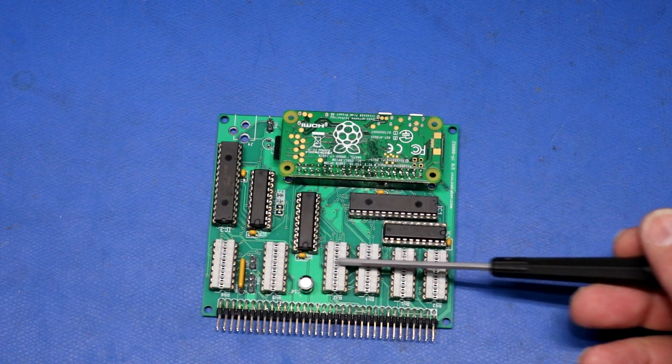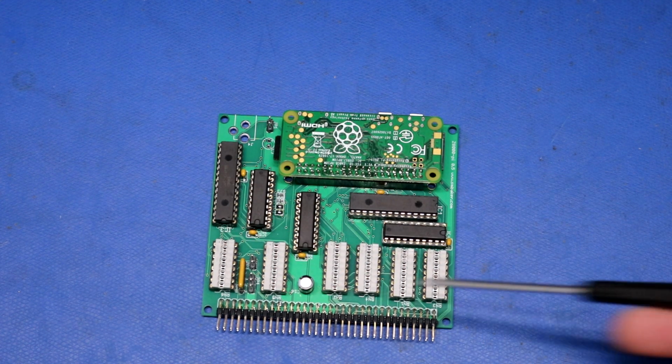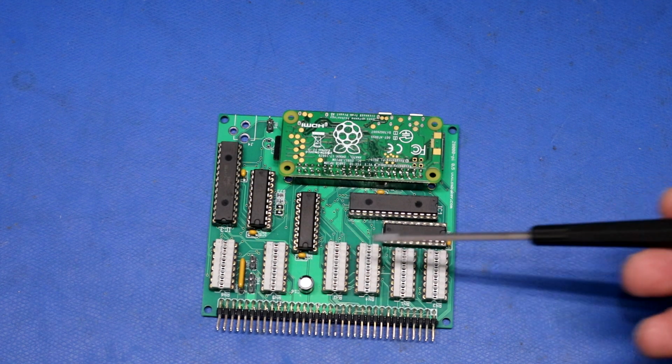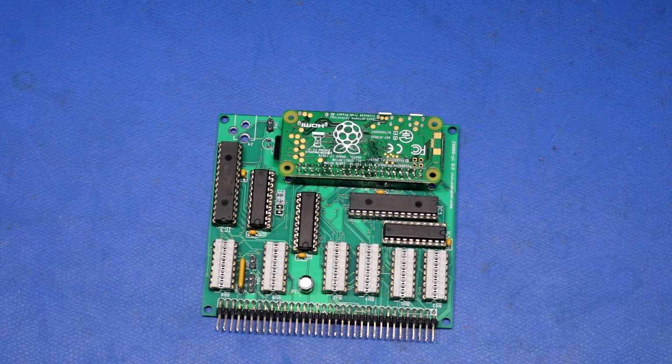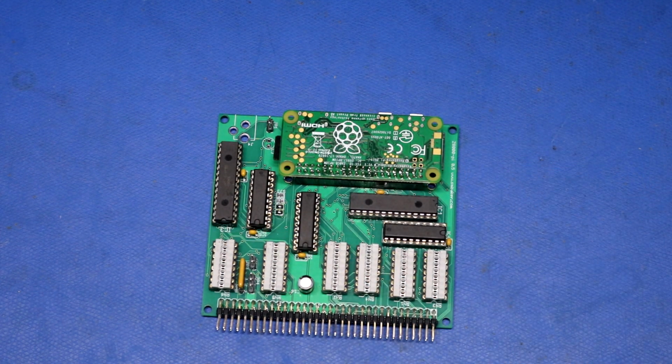This here will be removed, these shunt blocks, from the future revision of the board. They were so I could put resistors in there just for safety purposes so we don't fry anything. But once you get it debugged, you don't need resistors anymore. So these are just straight shunted across. Ignore them. Then we have various buffers as well as a pair of MCP23017 chips. Relatively straightforward build. Next, we have a speech synthesizer board.